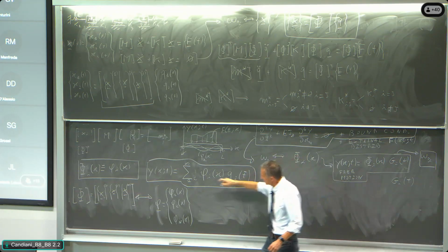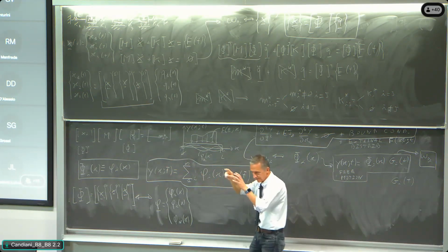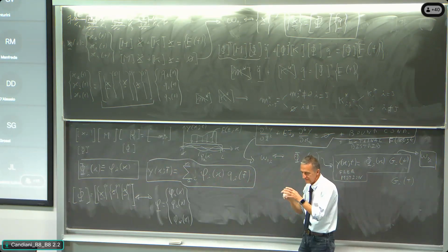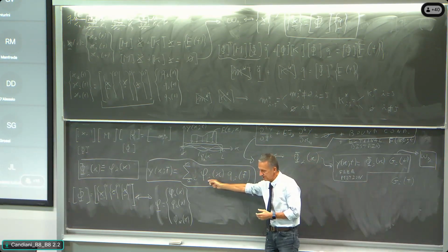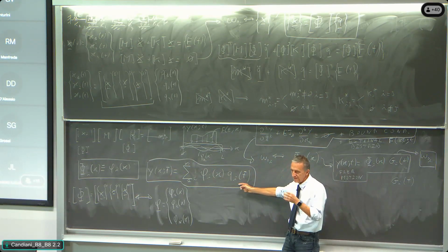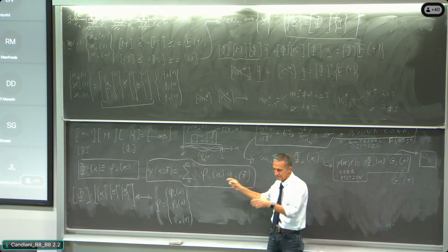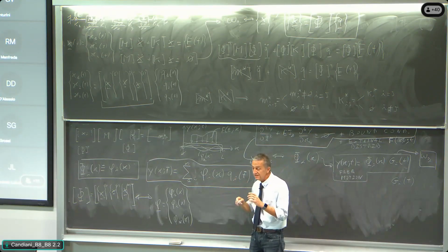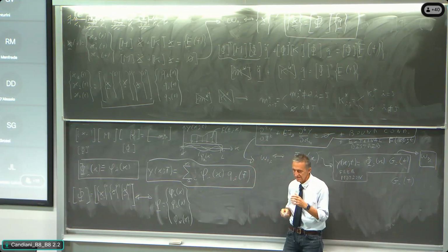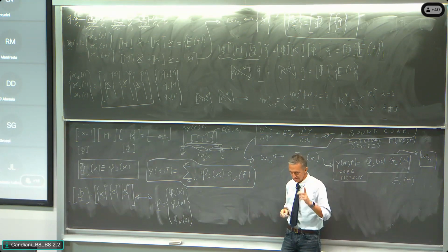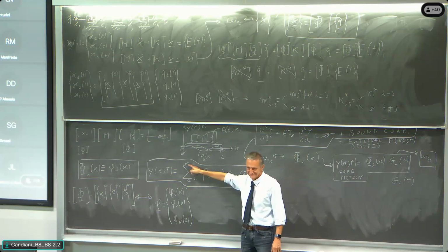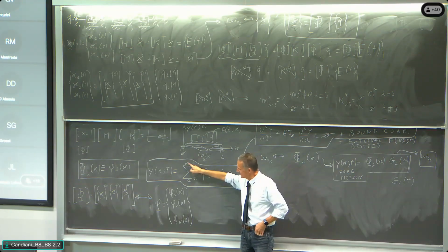So what I say is that if I fix the plot of the structure at a certain time, I am simply multiplying each modal shape by one real number: a real number for modal shape 1, a real number for modal shape 2, and so on. And the point is that I am using all the modes, and here is infinity.